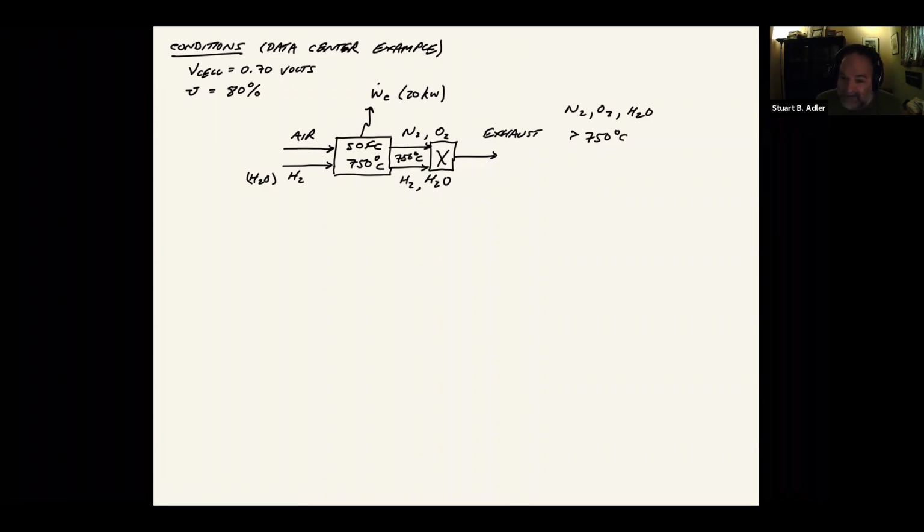But in many cases, it's something that we're going to specify because the fuel cell materials, for example, the electrolytes that we're going to use, their conductivity is really sensitive to temperature. And also the kinetics of the reactions of the electrodes are really sensitive to temperature. So we don't want the gases to go in too cold. It needs to be minimally the temperatures at which these cell materials will actually operate. And for an SOFC, that's somewhere around 550 degrees C.